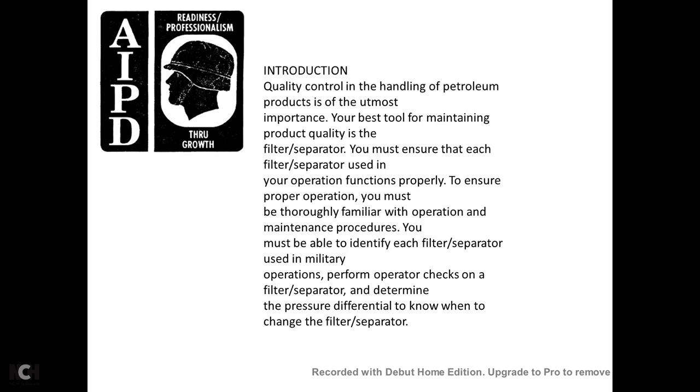Your best tool in maintaining the product quality is the filter separator. You must ensure that each filter separator used functions properly to ensure proper operation. You must be thoroughly familiar with the operation and maintenance procedures. You must be able to identify each filter separator used in military operations, perform operation checks on the filter separator to determine the pressure differential, and know when to change the filter separator.